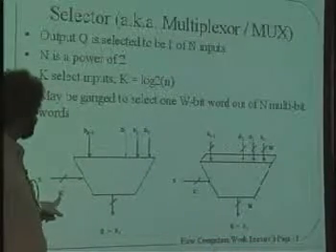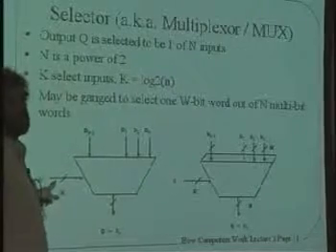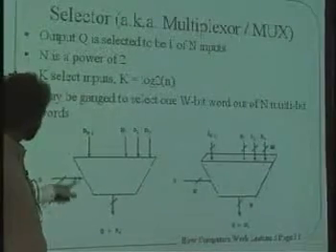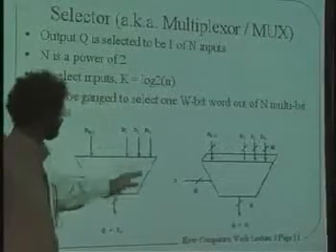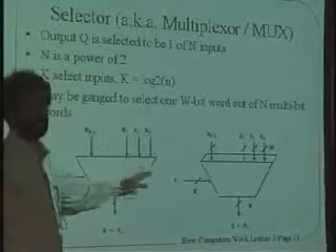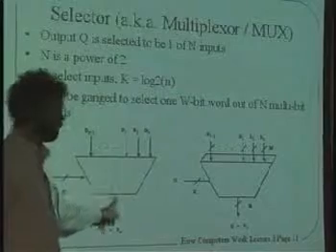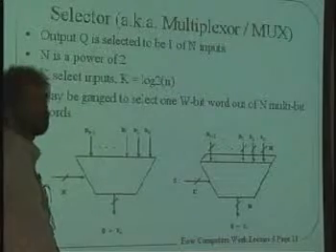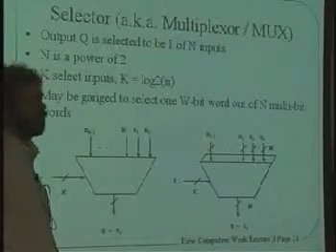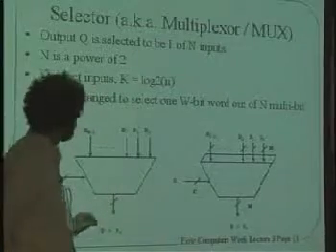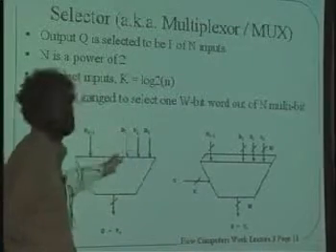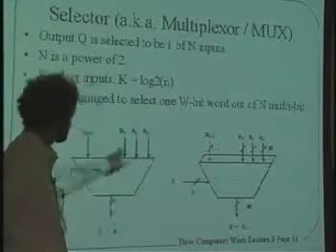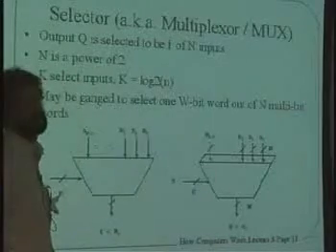If it has k bits here, in general there are 2 to the k different combinations of ones and zeros you can put into S. And so a k-bit input as a selection into one of these selectors will be able to choose one of 2 to the k different inputs to be passed through to the output. It's very much like a switch in a railroad yard, where we have one output track for the data to go on and several input tracks that a train may come in on. And we want to choose which way the track is set so that the train will be routed to the output, again, depending on how k is set up.